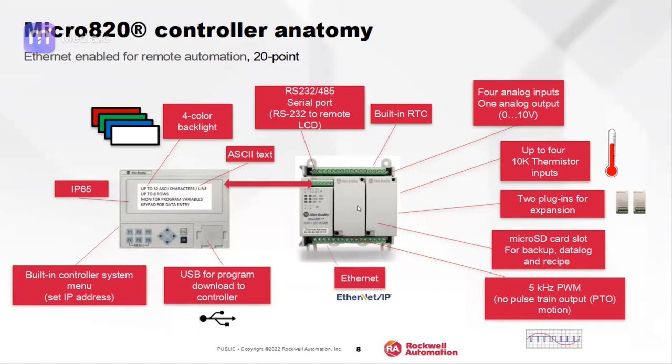It comes with a built-in RTC. It supports 4 analog inputs, which only support voltage input. We can use them for thermistor input also. We can expand IOs through the plug-in modules. On the top of the controller, we can add plug-in modules and expand either analog or digital IOs.